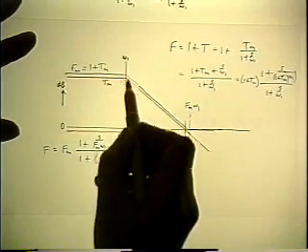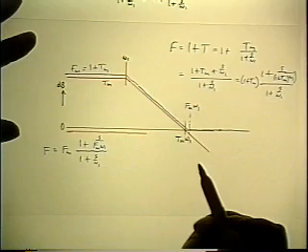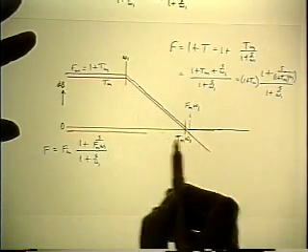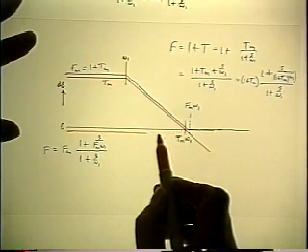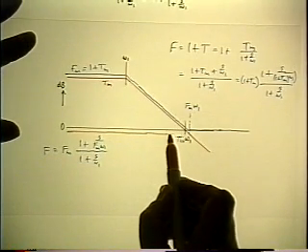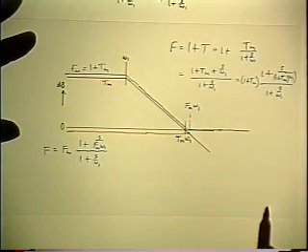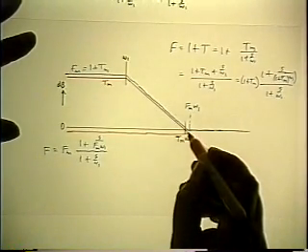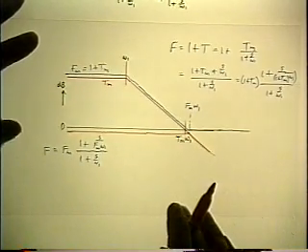And since the blue and the red line have the same pole at omega 1, the orange line doesn't even show it. When I subtract one from the other, the difference is the same. And the difference remains constant until you get to this frequency where the blue line levels off and the red line keeps on going. And so now the orange line simply follows the T because the blue line is at 0.